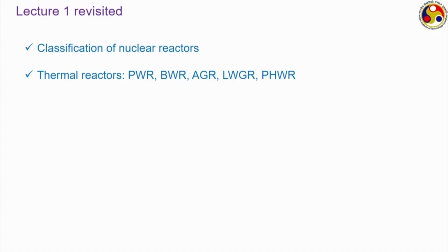Then the boiling water reactor, where water is allowed to boil and the corresponding steam can directly be supplied to a turbine to get the direct power output. So, here water plays the triple role of moderator, coolant and also the working substance. This PWR and BWR are the two most common types of designs. Then we can also have advanced gas cooled reactors, where we have graphite as the moderator and generally carbon dioxide as the coolant to satisfy their compatibility.